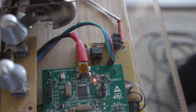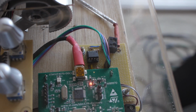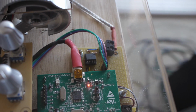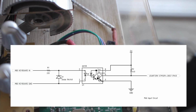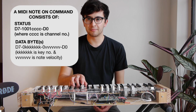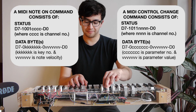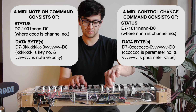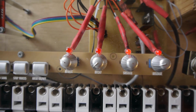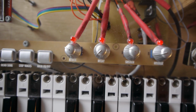Connected to the board is a MIDI optocoupler circuit. This allows the board to read MIDI messages from the connected keyboard by converting current signaling to voltage signaling. Here's the schematic for that. An example MIDI message could be a note on command, or a command signaling that a control parameter had changed. Four LEDs are connected to signify the current state of the ADSR envelope that modifies the volume of each note.